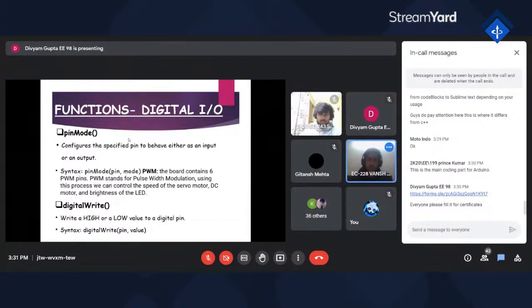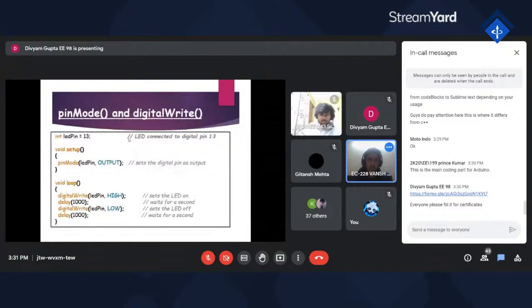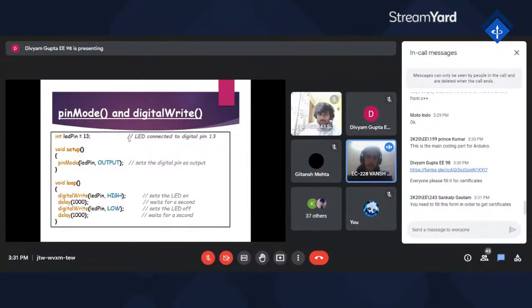ठीक, next slide please. राइट, तो यार इनको समझते हैं हमने क्या करा. First हमने एलईडी कनेक्ट कर दी अपने पिन नंबर 13 से. तो हमने पिन नंबर 13 यूज करनी है. तो what basically we do, we use an int data type because we are using numbers, तो हमने int में बेसिकली डिफाइन करा, और हमने एक वेरिएबल यूज करा उस पिन नंबर को रिकॉग्नाइज करने के लिए. तो we use a variable led pin and assign it a value 13. तो हमारी पिन नंबर 13 का नेम क्या होगा?